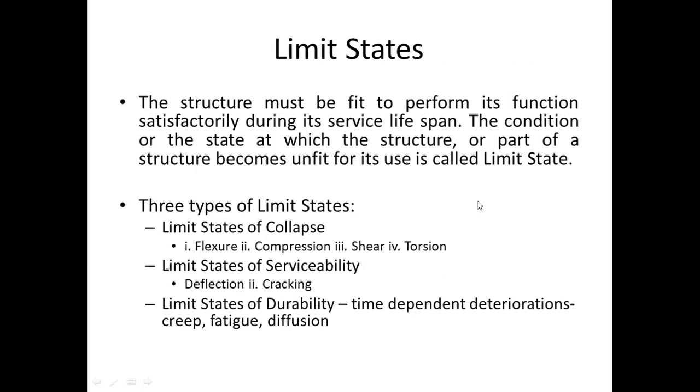So what are the types of limit states available over here? There are three types of limit states. The first is the limit state of collapse. What are the cases in the limit state of collapse? Fracture, compression, shear, and torsion. In the limit state of serviceability, deflection and cracking. In the limit state of durability, time dependent deteriorations, creep, fatigue, and deficiency all come in the durability cases.